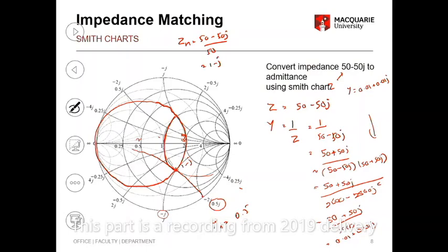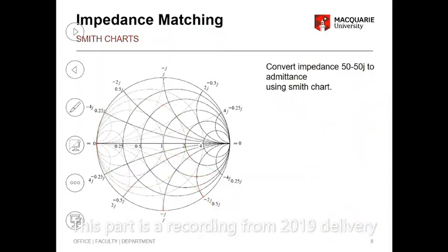Okay, because from nodding heads, I think you guys didn't understand it. Okay, so let me do this. So remember this number. I'm going to erase that. So this is the answer we should get at the end. So if I clean this up and then go for that. So if I normalize an impedance, 50 minus 50J, and normalize means divide by 50, I get 1 minus J, right?